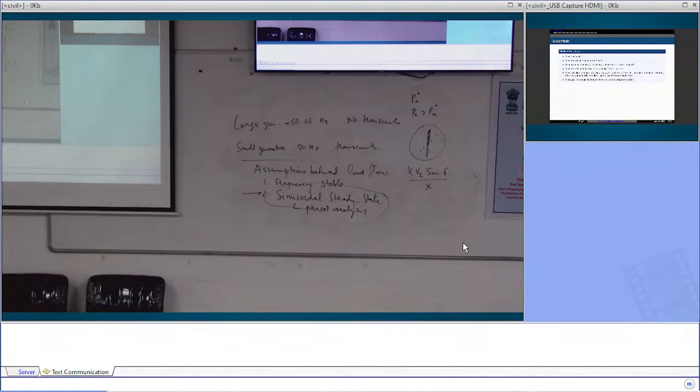What did we learn in the morning? We have got linear systems, right? Although this is a non-linear system, because those oscillations are always small, we can use linear theory, and all the things we studied before come directly to help us. So we do voltage regulator, same story. The power system stabilizer, exactly the same story. You apply a sinusoid disturbance, find out the change in power flowing and change in oscillations, the oscillation of the voltage or current, and then you damp it. Exactly the same story as we had before, right?